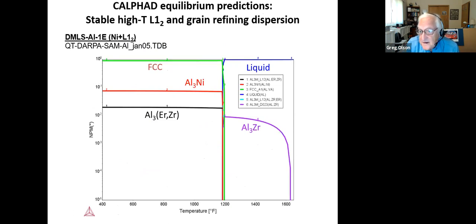And then there's the matter of actually exploiting the unique characteristics of printing, particularly laser fusion processes, where we combine boiling melts with very rapid solidification. And our best example of designing for that to achieve microstructures that could not be achieved by wrought processing is an L12 strengthened high temperature aluminum, where in this case, as shown by the equilibrium phase diagram here, in the ground state structure, we exploit an aluminum nickel eutectic for the hot tearing resistance and get a dispersion of multi-component L12 phase.